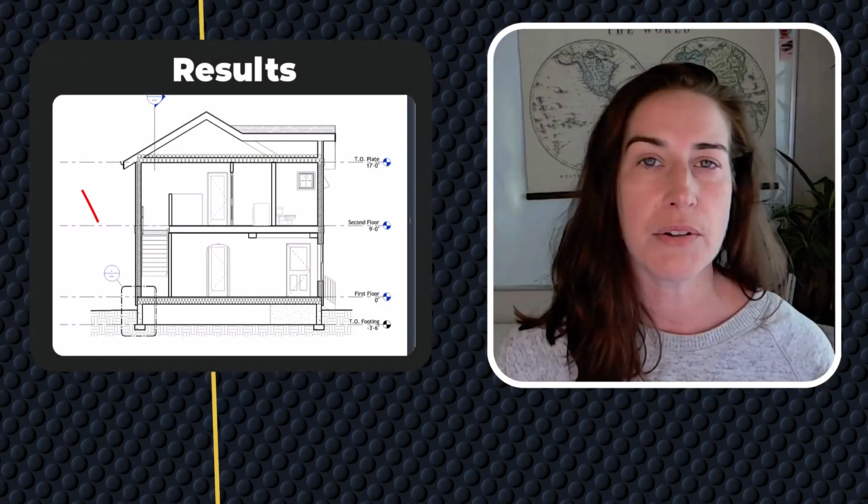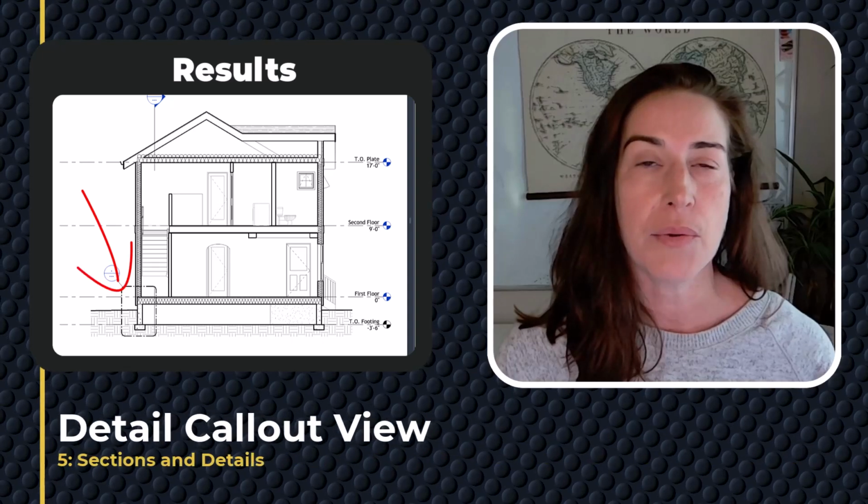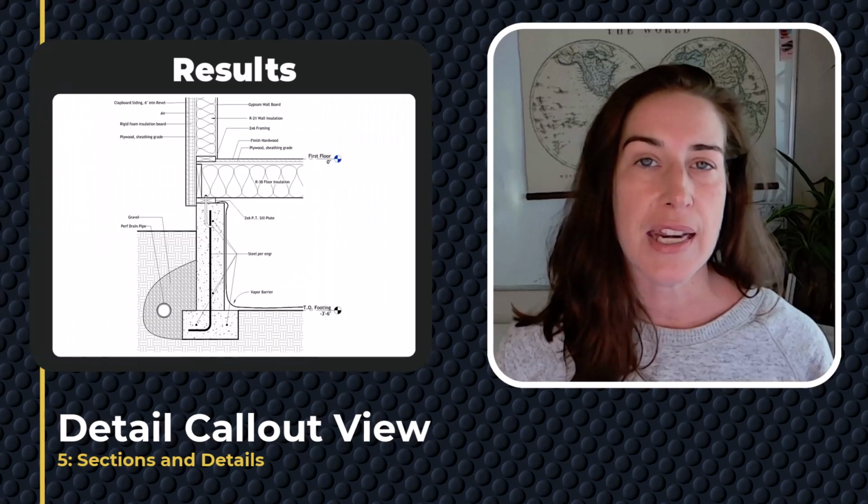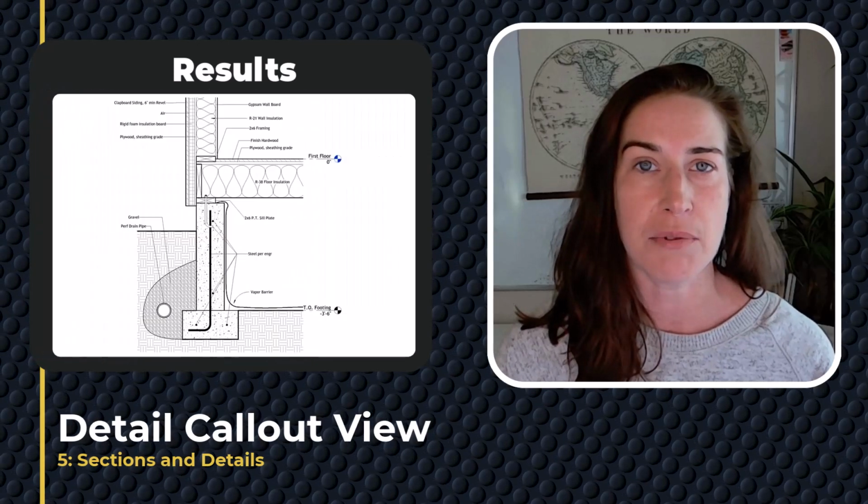In this video, we created our foundation detail. We started in the section view to create a callout view. We then added a few 2D elements to refine our detail.